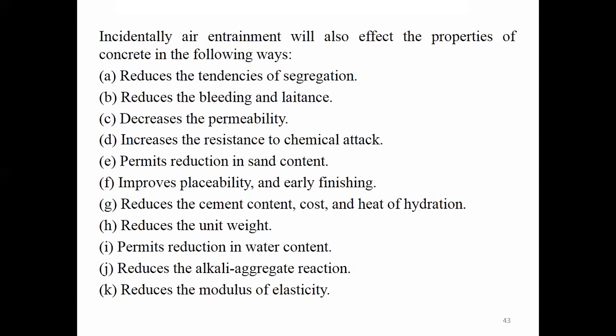Think about it: some of the volume of the concrete is occupied by air bubbles, so obviously the cement content, sand content, and water content will all get reduced. You know what is meant by unit weight, the weight of the concrete per unit volume. This is also affected by the air bubbles. Whenever you incorporate some amount of air into the concrete, the unit weight will get reduced, because the concrete is less dense.